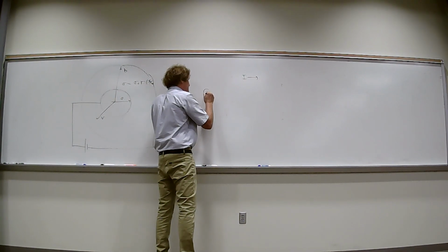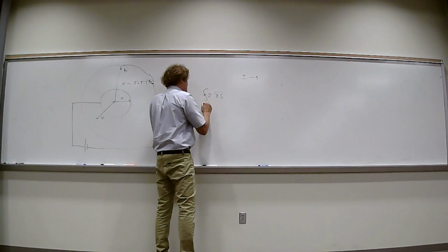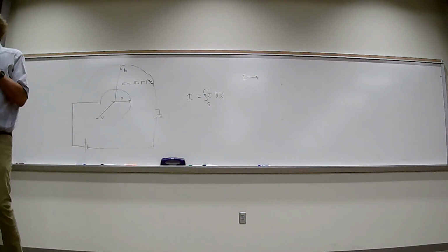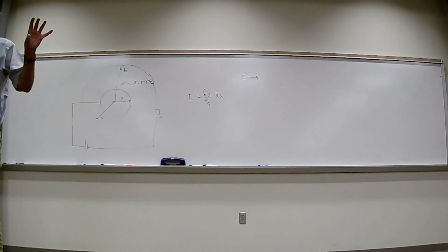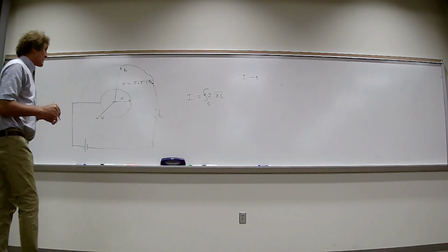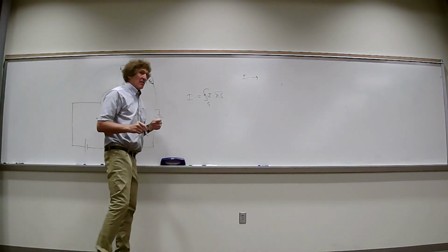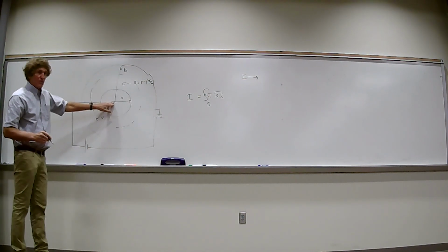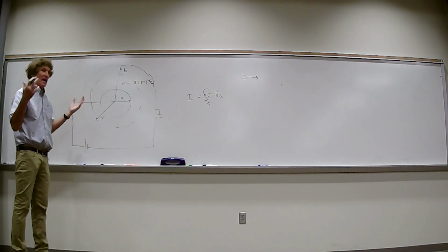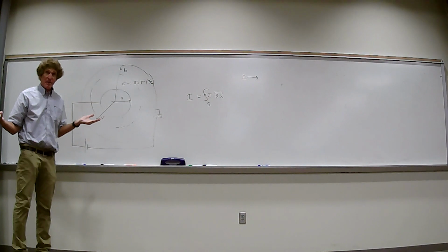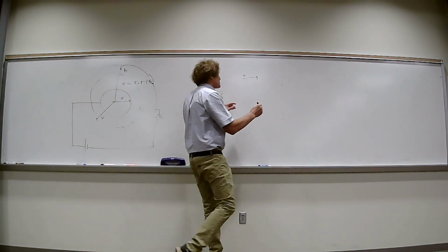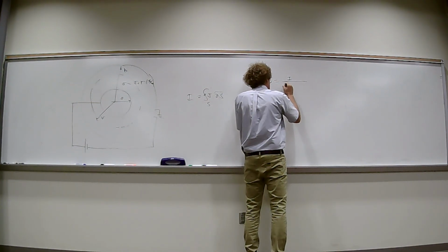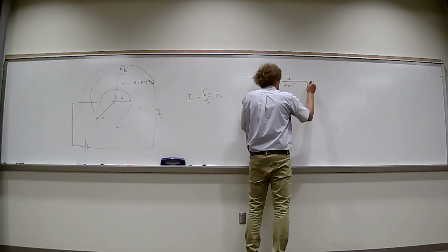The integral of J over the surface, closed surface, is the current flowing through a surface. It's identical to Gauss's law. Remember the integral of D dot dS was the charge enclosed? Well, here, the integral of J dot dS is the current enclosed. Now, if we have a spherical surface of radius r, all the current flowing from the inner surface to the outer surface has to pass through that surface. Does that make sense? So from I I can get J, and that's simply equal to I over 4 pi r squared, in the a_r direction.